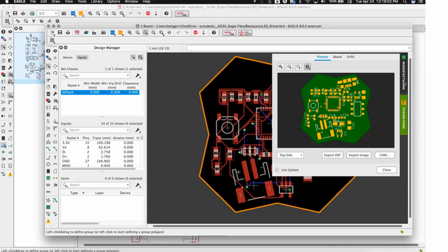Yeah. What I've been doing is importing them to Fusion, and then exporting as polyline, and using that extend command that they added. That way I can close them, and then I can import from there into Eagle. That's what I've been doing lately. Yeah, because Fusion has a good export for polyline-based DXF, which we support perfectly, and that one works. As far as importing DXF fills as polygons, you currently have to rely on existing ULPs. Definitely there's been talk of being able to convert contours to polygons within Eagle, but that command hasn't been implemented yet.